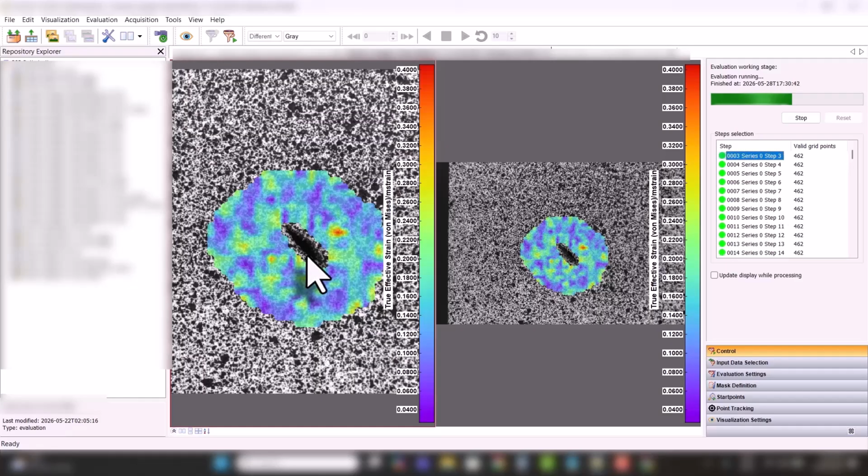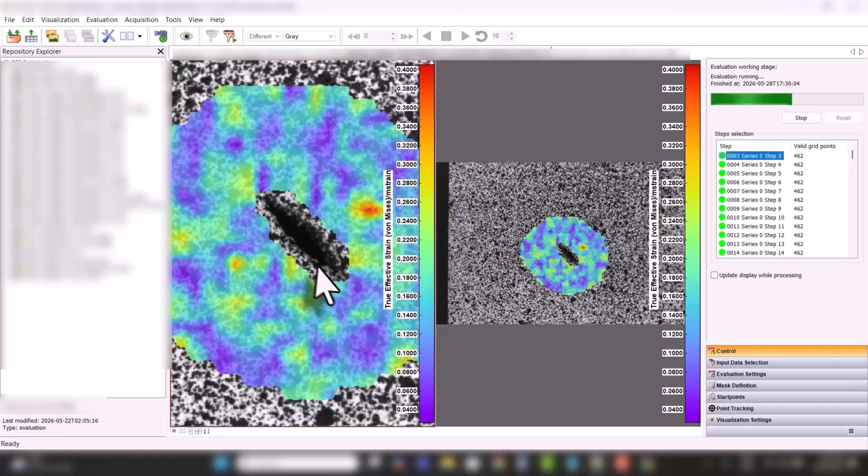Okay, and there we go. We got even closer. Look, we're almost right at the notch tip. Okay, and when this finishes, you would probe and see how these precisions look, if the precision is acceptable. Because we lowered the facet size, right? That's going to, in general, lower the precision. But it might not even have lowered it much at all. You have to see. Just depends.